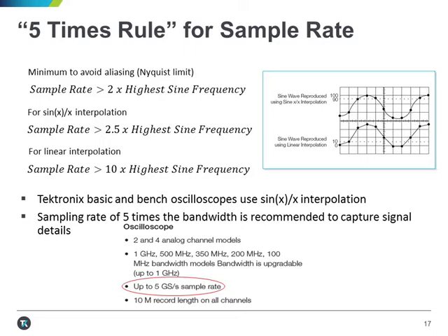At the fast time scale settings, the scope will interpolate between samples to fill in the trace. Most Tektronix oscilloscopes use a sin(x)/x function to fill in the spaces between the samples. This type of interpolation is optimized for sinusoidal waveforms, which from our discussion of bandwidth and from school, we know are the basic building blocks of complex signals.